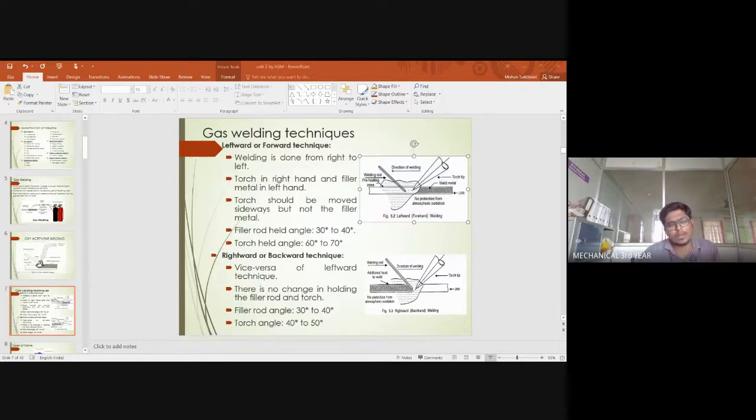So you can see only some amount of flux is being used during the welding operation. Since the flux is supplied in a greater amount, only a small amount is used when the welding is happening. The other flux can be sucked back and reused with the help of your vacuum system.